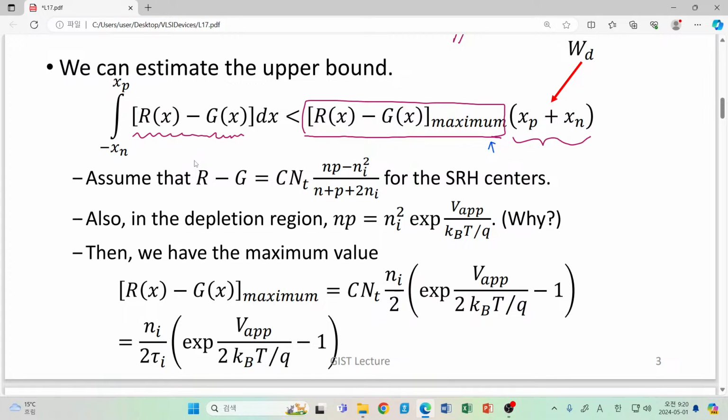That is the point. So this form of net recombination is given by, of course, a certain coefficient which depends on many different things, but the most important part is simply given by this product, np minus ni squared, the difference between np and ni squared. As I told you repeatedly, if this is larger than 0, it indicates that excessive carriers are coming into the scene.